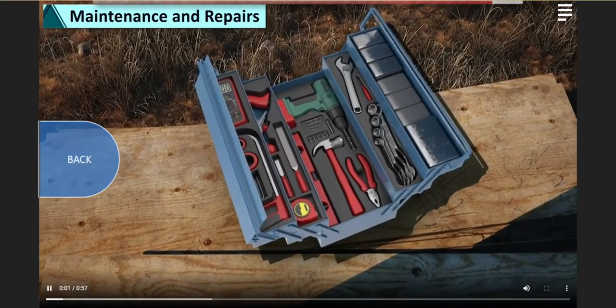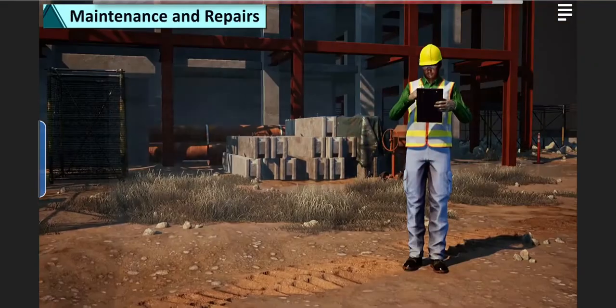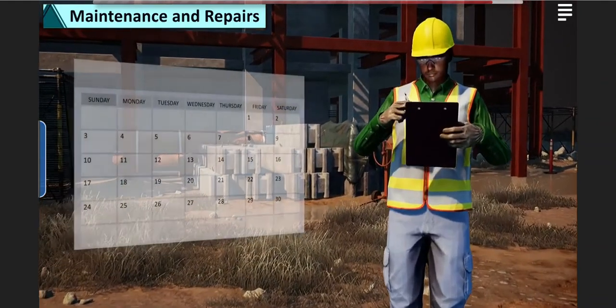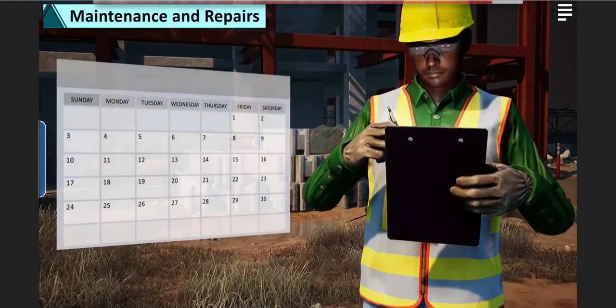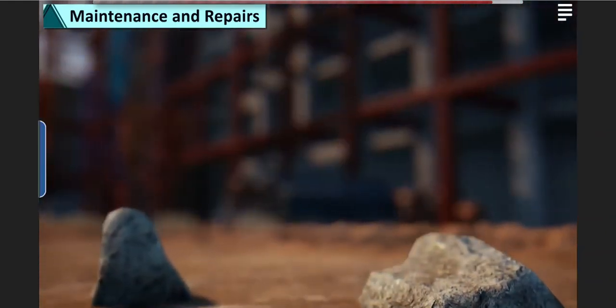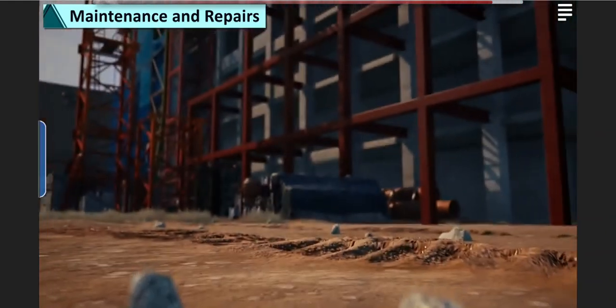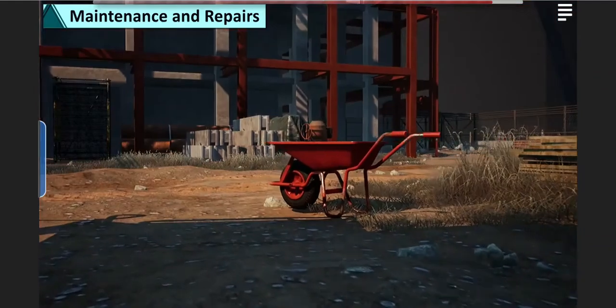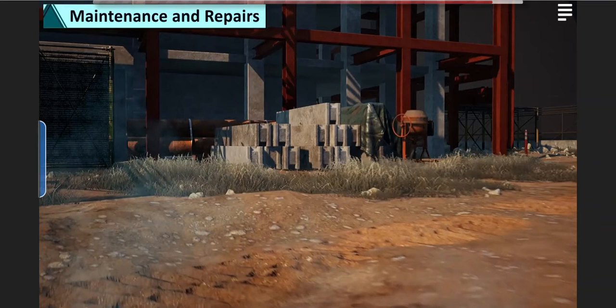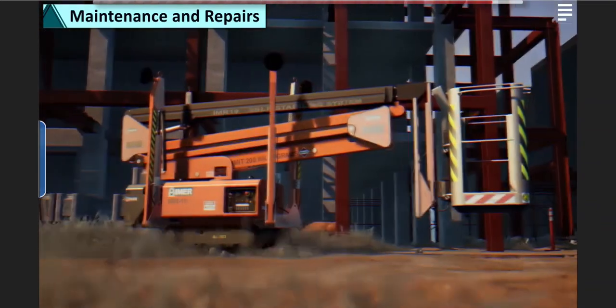Timely maintenance is vital to preventing problems with the MEWP. All inspections and scheduled maintenance required by ANSI or the MEWP manufacturer must be carried out on a regular schedule by a qualified maintenance technician. This schedule must take into account the environment in which the MEWP is being used and any environmental factors that might speed up wear and tear, such as extreme temperatures or the presence of corrosive gases.